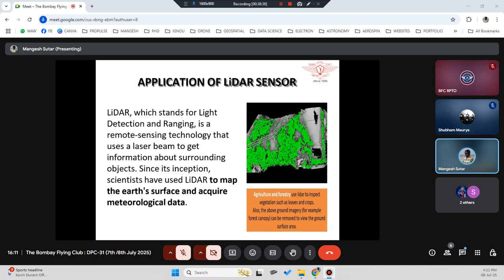When the tender document was made, they had called only 1 or 2 drone vendors, and they suggested: get the footage of RGB, thermal and lidar. But they didn't define what you would capture with lidar in thermal. Because there we don't need to capture any elevation. Lidar is basically to acquire meteorological or geological data kind of things only. Otherwise normally in power line towers you don't need lidar. If you are only monitoring vegetation, you can do it using RGB cameras also. That is what we convinced the board.